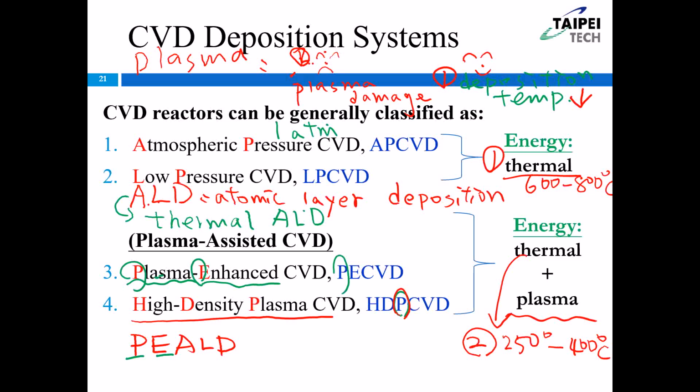In industry, thermal budget is quite important in an IC fab. So a low deposition temperature is very important to have a small thermal budget. A small thermal budget will allow you to have accurate oxide thickness, and also we can control the junction depth of the source drain.